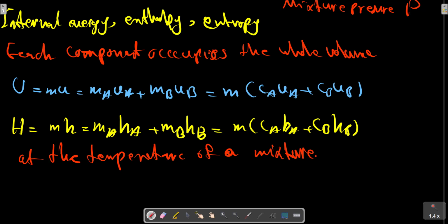For a process involving a change of temperature, the changes in these values are evaluated by one of the three models discussed in the previous section, involving either the ideal gas tables or other methods. In a similar manner, in these equations the mixture energy and enthalpy could be expressed as the sum of component mole fraction and properties per mole.